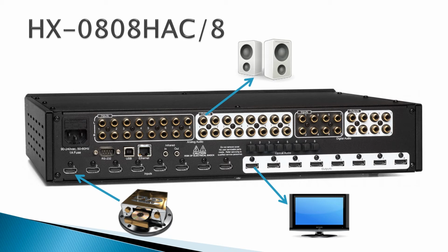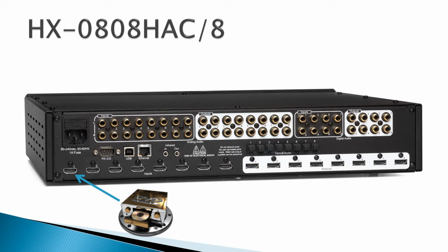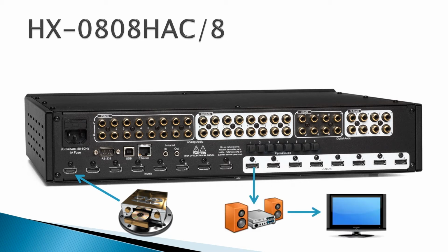However, let's step up the complexity here, and now let's take that same Blu-ray input, single input, and let's come out of that same HDMI output, but this time we're coming out 7.1 surround sound, let's just say. And now, because of the conversion capabilities, we're also capable of coming out any or all digital audio outputs. And in this instance, let's just say we're coming out to another surround sound zone in 5.1. Well, this switch is not going to downgrade your HDMI input from 7.1 to 5.1 because it's capable of distributing that audio to different zones and different formats simultaneously.